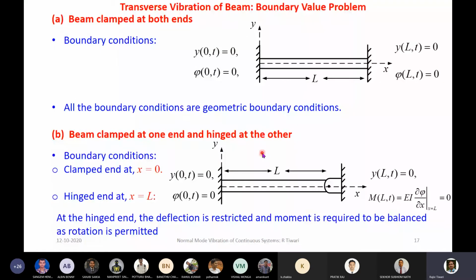So here, let us say we are considering a beam fixed at both ends. The axis is x this, y this. So this is the x equal to 0 position. This is the x equal to L position. Because this is fixed at both ends, we expect that there is no deformation here. The displacement will not take place at the 0 position. So the displacements at both ends are 0. Because it's fixed, the slope also will be 0 here and here. So the slopes are also 0.